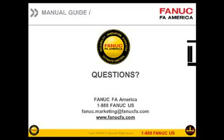Now with a buttress thread, most of my experience with those is that typically the backside angle is actually in the insert itself. And so you can set up the front side to be the correct angle for the buttress thread, and then it will actually form the backside of it based on the insert itself, Mark. That's how it does that.